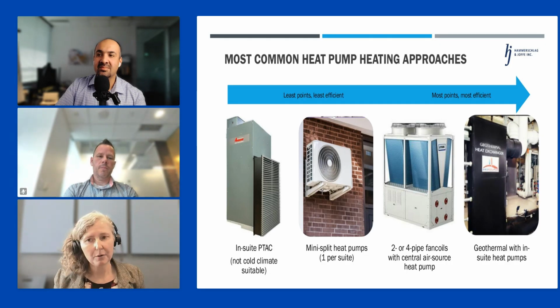There are some cold climate versions coming out of a couple of manufacturers out of Italy that use sleeves through the wall, like 2 cores this size. Those are really interesting. They're only available in a 1-ton peak cooling size. So that is appropriate if you are doing all bachelors, maybe all bachelors in 1 bedrooms.